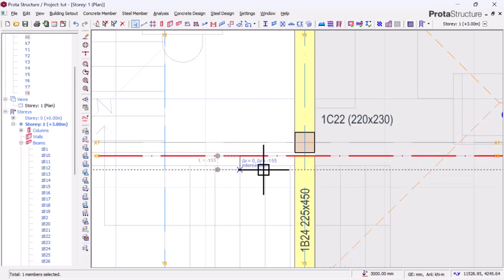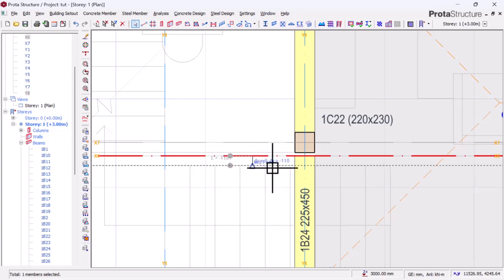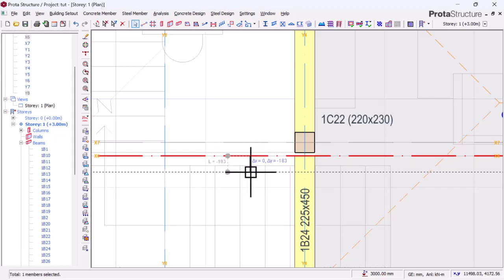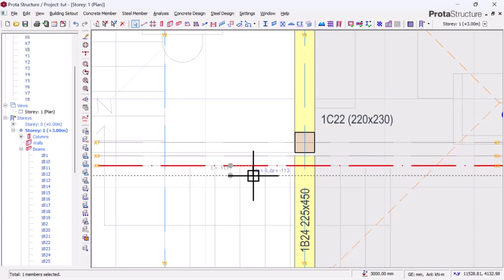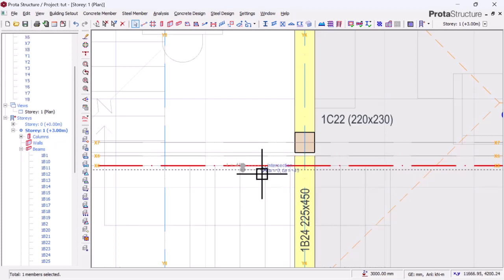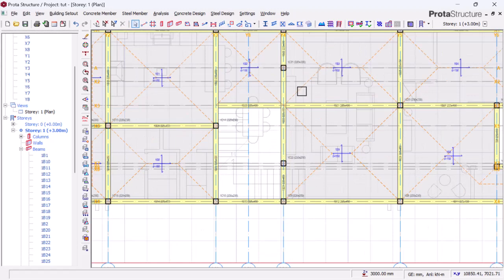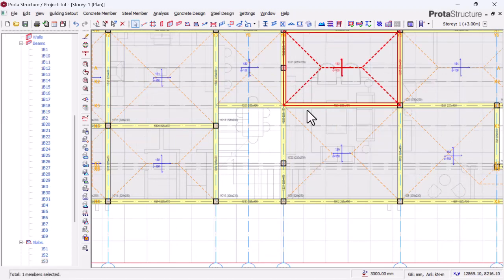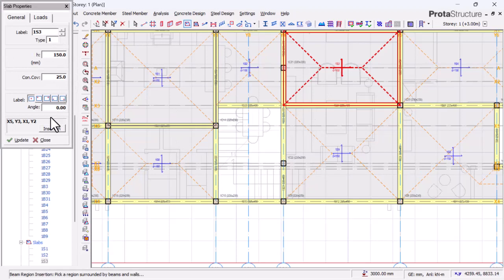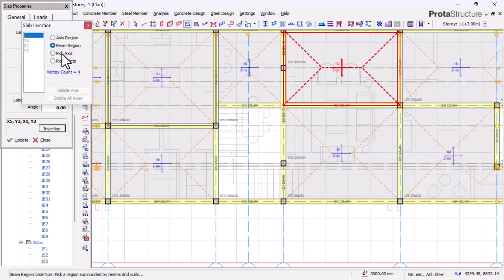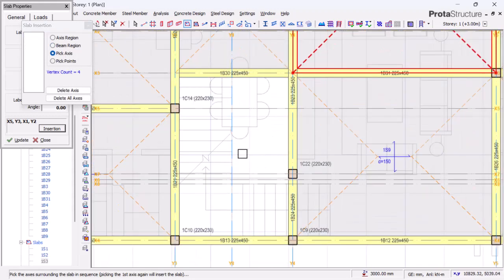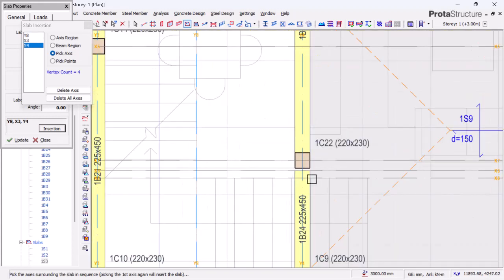We are trying to offset this to get this finishing distance. You can see the angle showing us there. You can click on that angle. It's the same length. So with that, we can escape. In this regard, we can also add the slab. We can click on this and check the properties, since we have similar properties, but we're going to change the insertion point to pick axis. We'll pick this axis, go on this, and get the boundary, the one we just offset newly, and click this.